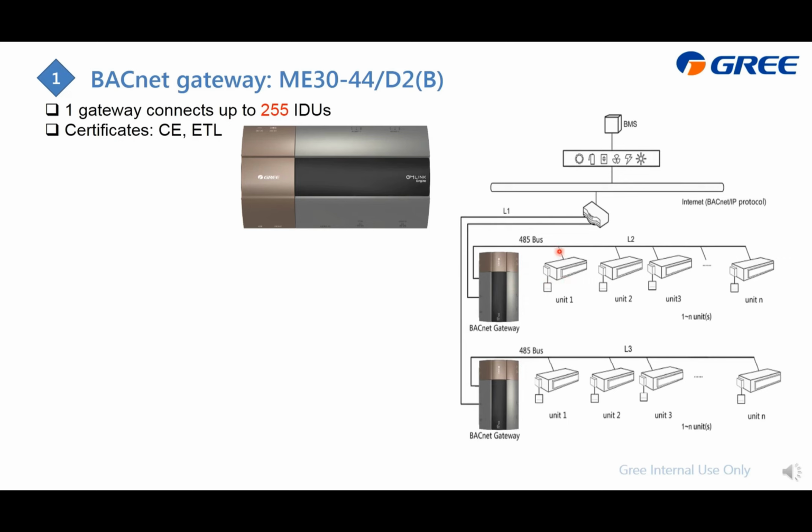Just connect them, which outputs the Modbus protocol. Then connect to this gateway and output from here to the PC if there is only one gateway. And if there are two or more gateways, we recommend applying this router for the combination, and then you can connect to the PC.